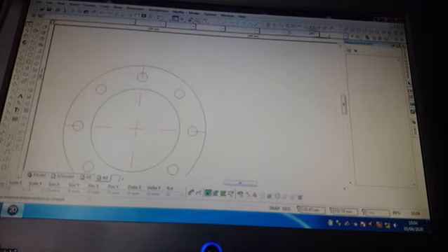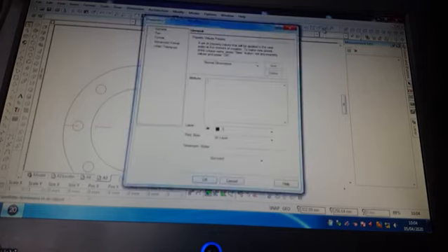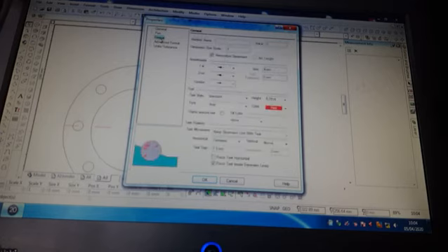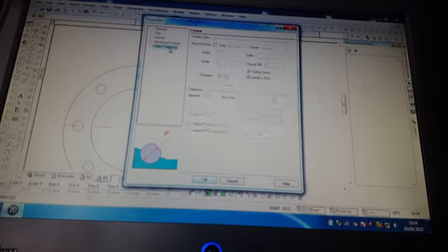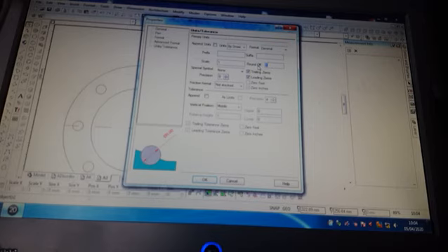So we'll look at the properties of the dimensioning by going right button on the toolbar at the bottom, get the extra menu, format. I think I'll change it to 5-point high, which is about 5mm on the A3. Yeah, I'll keep it as red, and I don't want to force the text inside the lines. I prefer it like that for my diameters. So my units and tolerance, I think I'll actually put a 0.01, and I'll round it up to 1 decimal place.